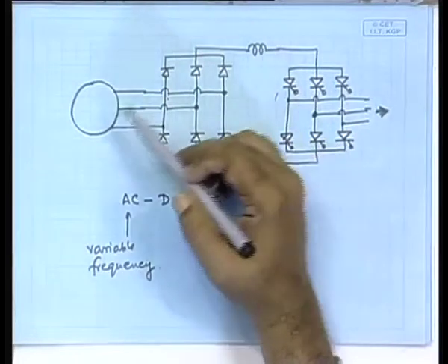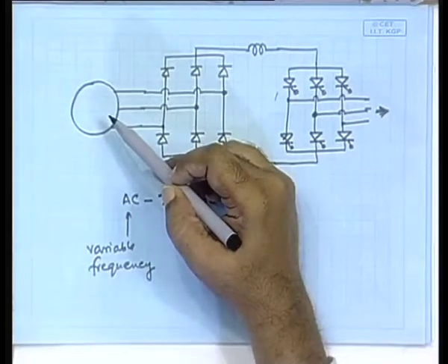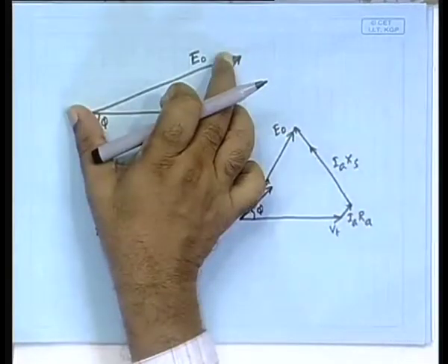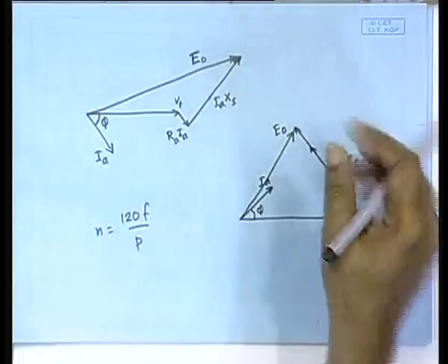In some cases people are also considering permanent magnet machines, where the field is constant, because as I told you, in a thermal power plant, the machines are not permanent magnet machines, because in order to supply a varying amount of reactive power, you need to vary this, and the way to vary this is by varying the field, right.